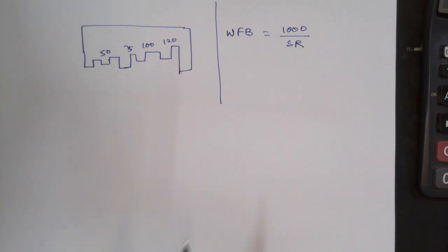Low paint volume solids will result in low paint dry film build being applied, and in that case you may have to go for 3 or 4 coats, so it requires more paint volume, and such kind of low volume solid paint will result in poor sealing, poor hiding, and there will be a loss of gloss, and it results in poor durability also.